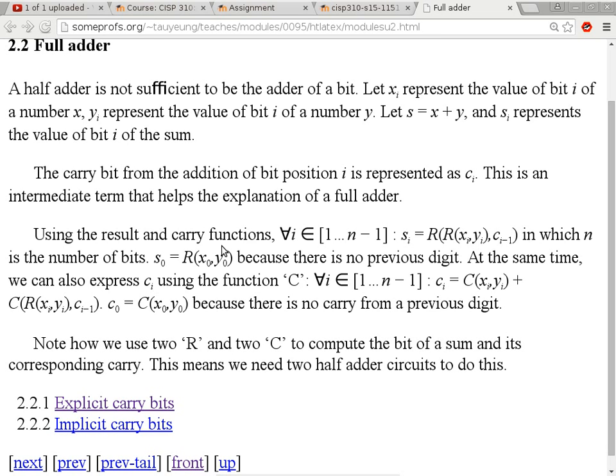Yep. So this is also called the carry ripple, because when you look at it, the carry bit goes from the least significant digit through the second bit, through the third bit, and so on. You can actually kind of envision how this bit is going to change its state as it goes along to the more significant digits. I guess the last one.